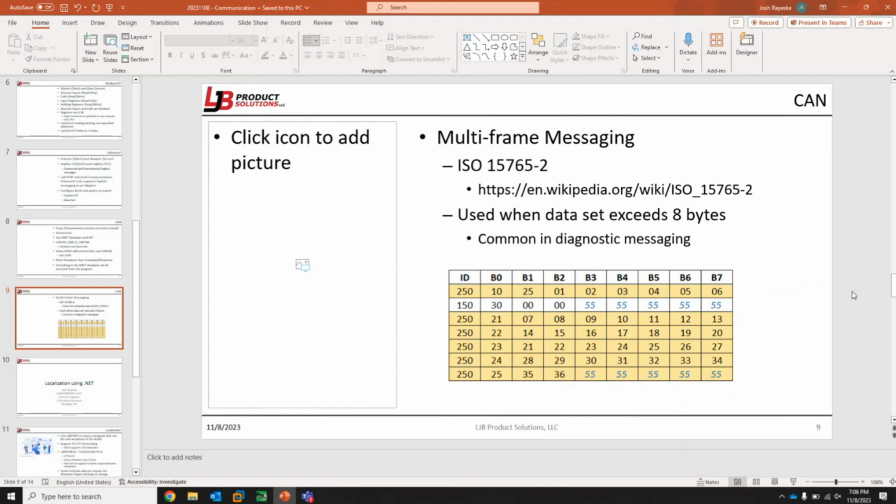Another one I want to say as a good practice that I try to use is put a heartbeat on the messages. So on the PLC, use its second counter or something and have that as one of the data elements. And same thing on your data going down. If you're using cyclic, have a rolling counter going. I know the PLC is always going to be monitoring that connection, so it'll be throwing error bits if it loses the Ethernet IP.